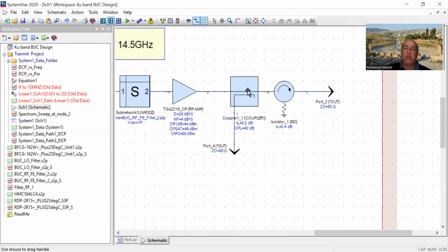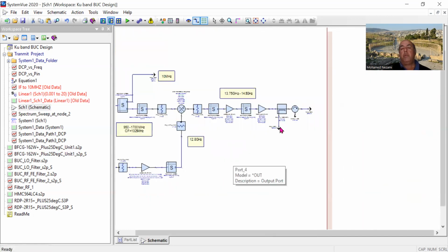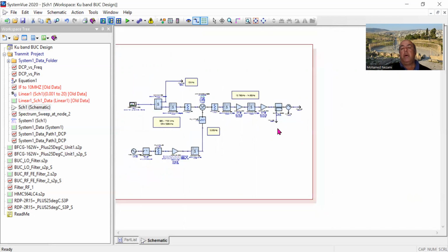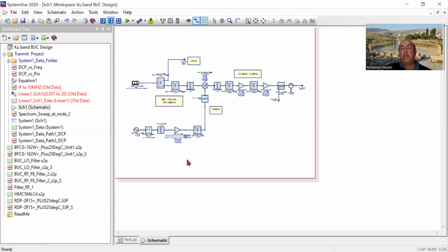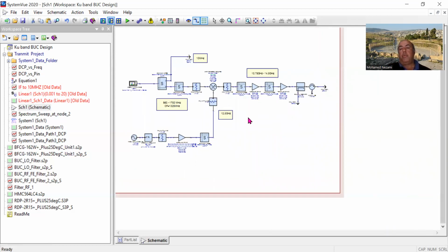Well, actually, this is a 40 dB directional coupler, and that's nothing but a quarter-wave edge-coupled microstrip printed coupler. The reason for it is we couple the signal to go into monitoring. We usually take this signal and detect it, and sometimes measure the relative level and display that, to send that over to the computer or the microprocessor or microcontroller that is housed in the BUC as a controller for